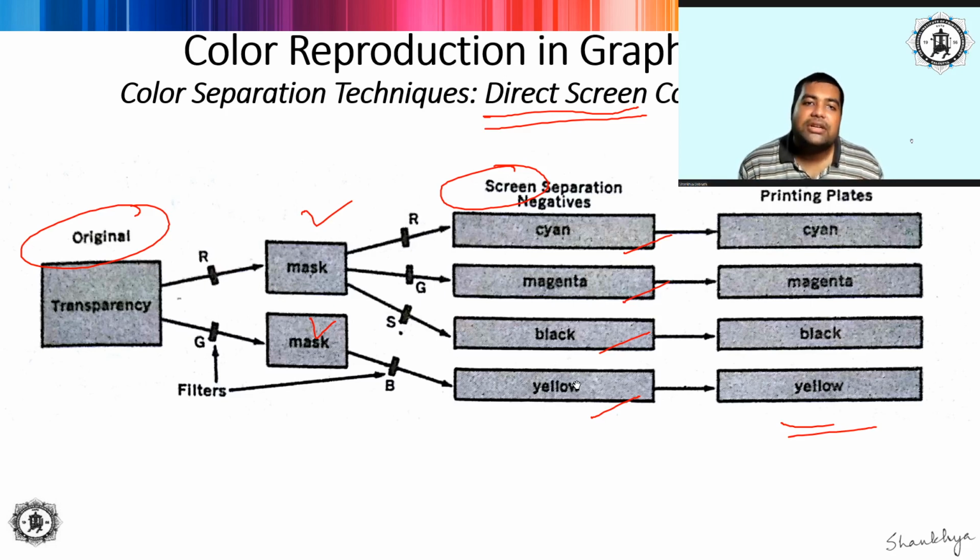Without the flash, shadow areas would not have received sufficient light from the copy to produce the dots, because the amount of reflection from the shadow areas is already very less. The reproduction would have looked kind of dull and dirty.